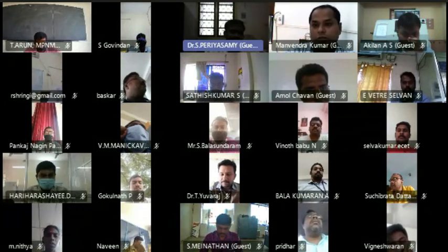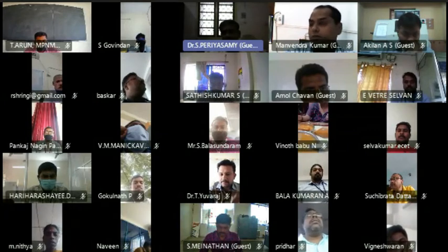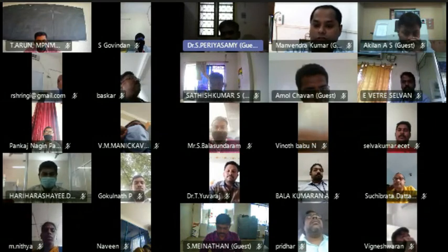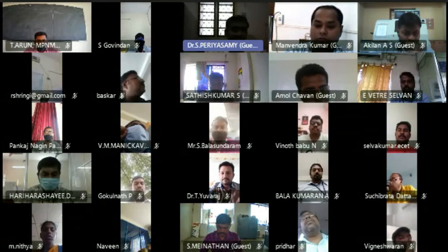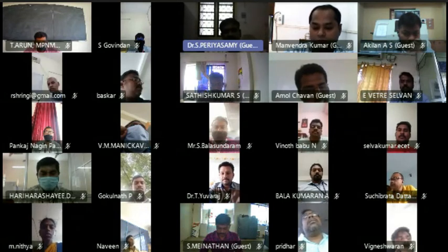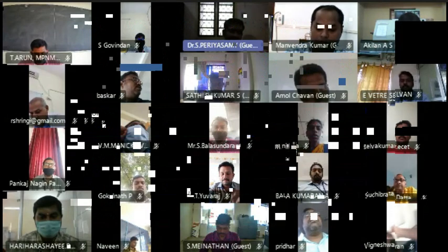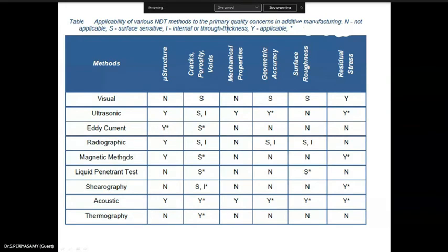Then the critical flaw types, sizes and distributions are not established. Even if you are magnifying 500 or 600 times, or to the nano level, Angstrom level, determining the size exactly is very difficult in additive manufacturing. There are also direct energy deposition methods, metal additive manufacturing, they may be the same. Even local people are using fused deposition machines with PLA material, ABS material, and other normal things.